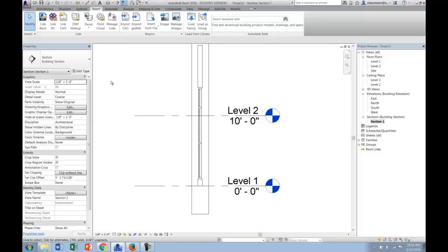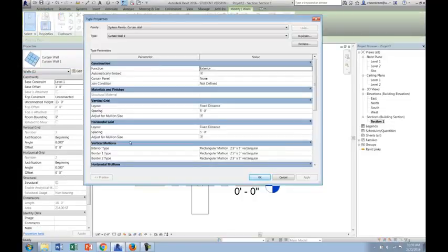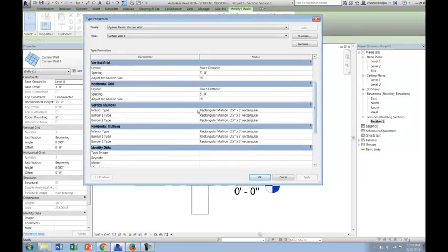system's working. So now when I go and select my curtain wall here and hit edit type, I can go to these mullion designations, where I've just applied a typical 2.5 by 5 inch square mullion. Now you can see listed here under my mullion options, I've got 6 different types for that FCO window system. One head, one sill, one jamb, which is going to be left, and one jamb, which is going to be right. It's hard to tell from their indications here which one is which. There's no L or R. And then one typical horizontal and one typical vertical.